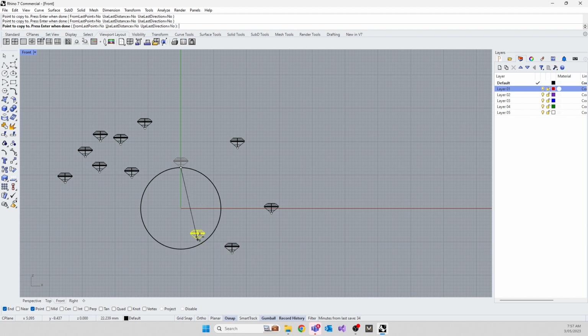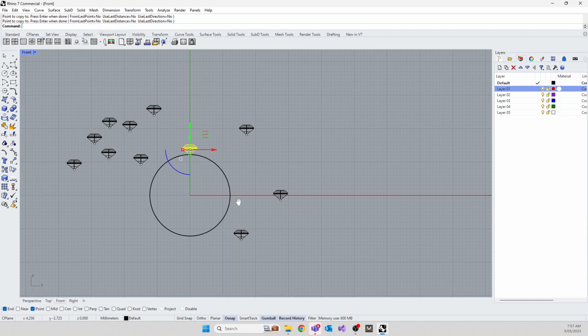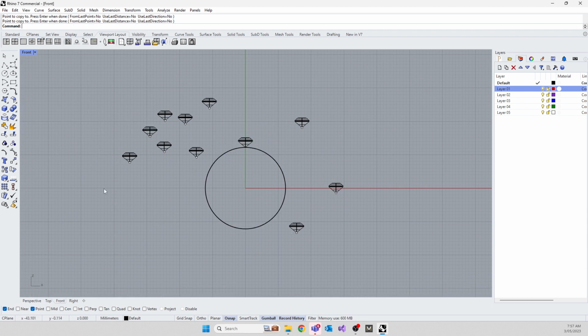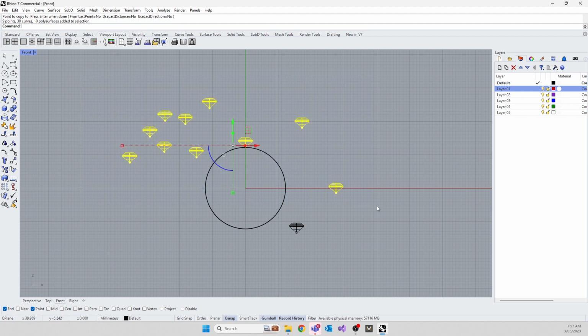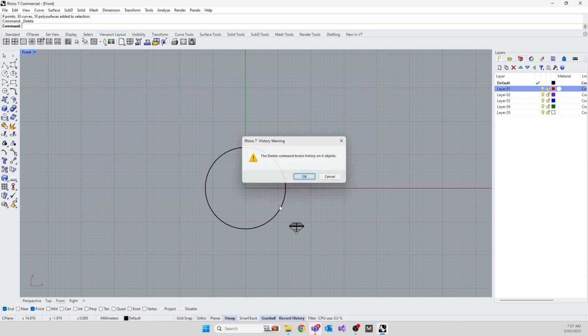They're object snaps, not snacks. I've got snacks on the mind this morning. So an object snap helps you snap one object onto another object. It's in the name, O snap. Now you'll notice on the bottom here, this menu is kind of out of the way. I'll explain in later lessons what the rest of these snaps do, tangency and that kind of stuff.